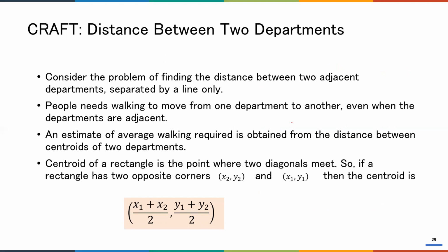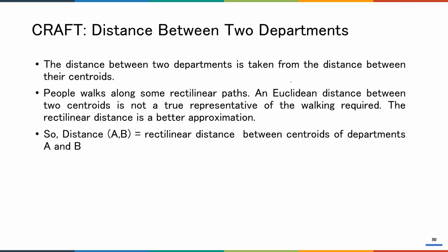So what you need to do first in CRAFT is calculate the distance between 2 departments. And as I explained before, there are several ways to calculate the distance. In CRAFT, we use the rectilinear path from their centroid.